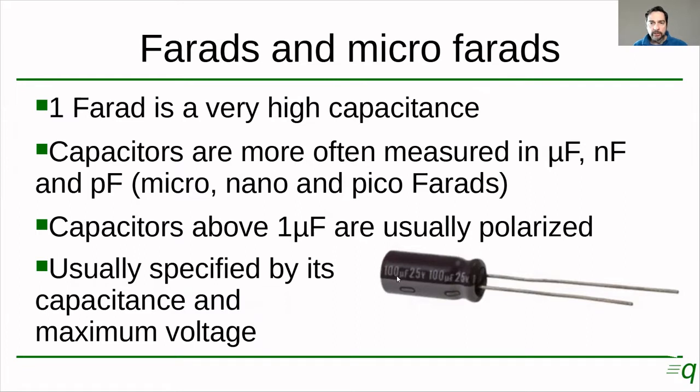This is a capacitor of 100 microfarads. As you can see, this is the negative terminal. This is the negative sign here, and it is next to this terminal. Also, this terminal is shorter and the positive terminal is longer.